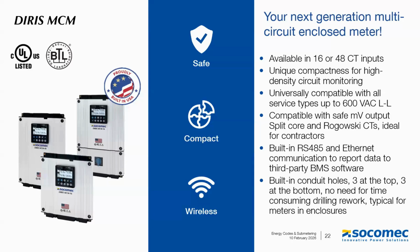So you can even monitor circuits from different voltage sources. If you have a 277 to 120 volt transformer, you can monitor loads on both sides and make the right correlation. It's really a cost-effective solution to monitor multiple circuits. So MCM 48: up to 16 three-phase loads or 24 split phase. We're starting to see some traction with tenant billing applications, which are split phase loads where you need two CTs, while one MCM 48 enclosure can be used to monitor up to 24 tenants.